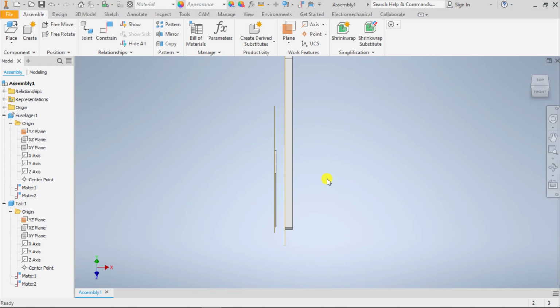And I can see here that unfortunately, on purpose, I did not extrude these parts symmetric. Back when we started talking about making parts, I said, if it's symmetric, make it symmetric. This is why. We can use these planes as a constraint reference, but not if they're not symmetric.